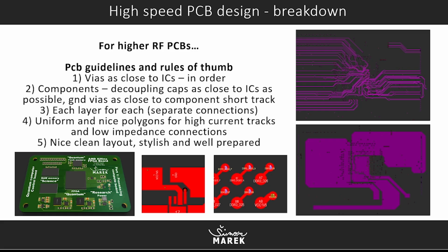You should have uniform and nice polygons for either high current tracks or some important ground planes and stuff like this. And they should be low impedance connections. Nice clean layout, and should be stylish and well prepared.